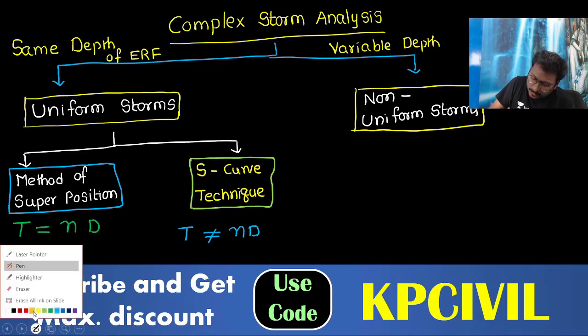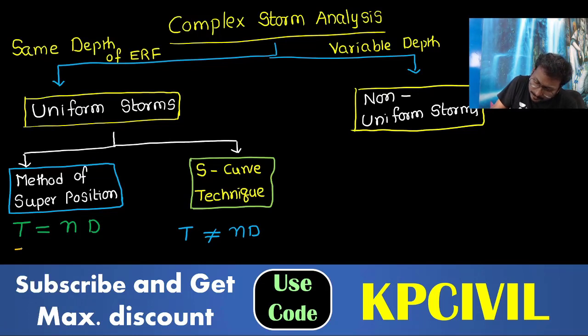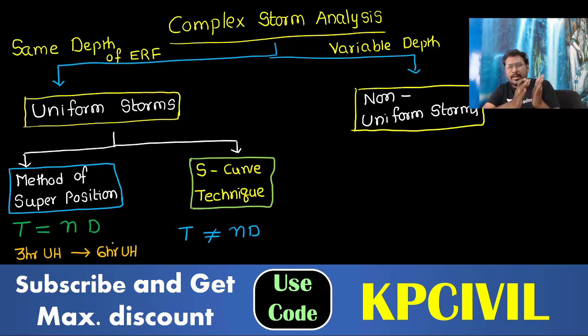If you want to convert a 3-hour unit hydrograph to 6-hour, 4-hour to 8-hour, 2-hour to 4-hour, 6-hour, 8-hour, use the method of superposition.